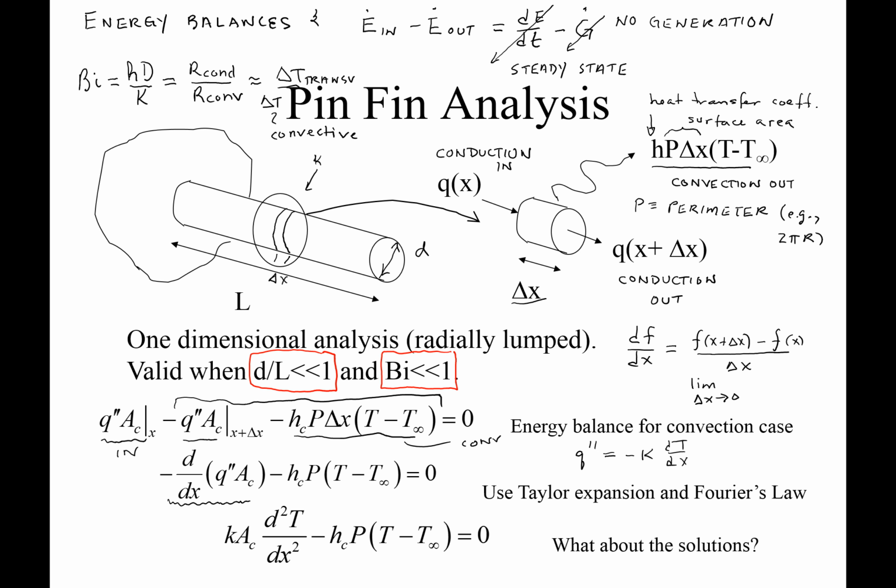When we look at the radial direction heat transfer rates, and these are in fact equal, the balance says that you have a relatively small conduction resistance and an accordingly small conductive temperature difference, and these are balanced by a relatively large convective resistance and a relatively large temperature difference between the surface and the free stream.